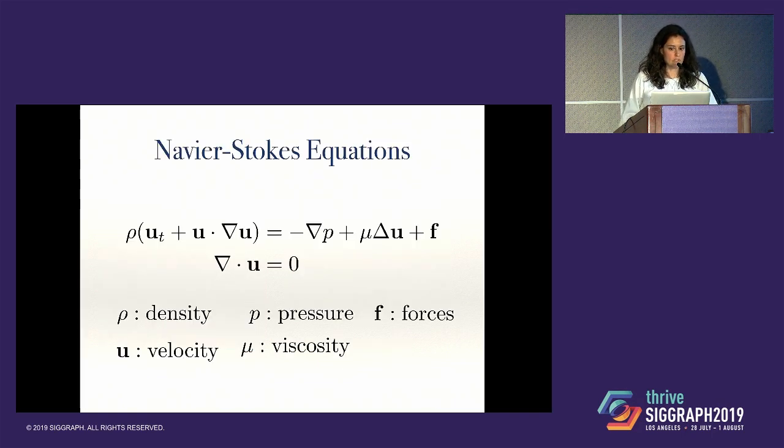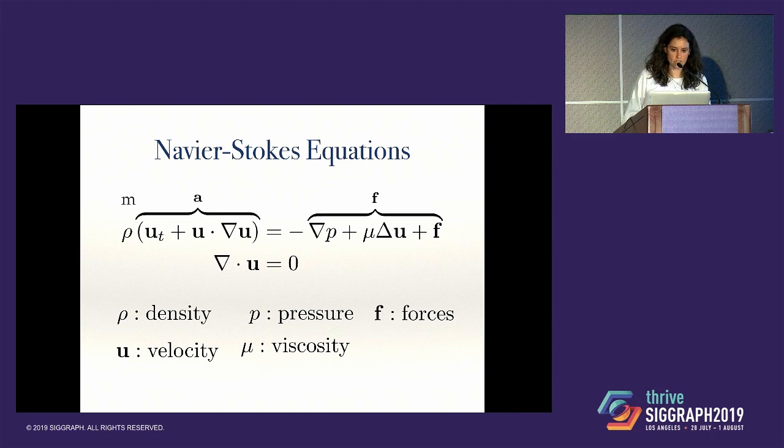The fluid equations that we're typically using are in a particular regime, and in the regime of intermediate Reynolds numbers, our incompressible fluids look like this. These are called the Navier-Stokes equations. And it's much more complicated than F equals ma, but it's actually a form of F equals ma. One difference is that these equations have been divided by volume. So rather than having units of force, they have units of force density. So instead of a mass, we have a mass density. And then on the right-hand side, all those forces are a force density, actually. So that should say force density, really.